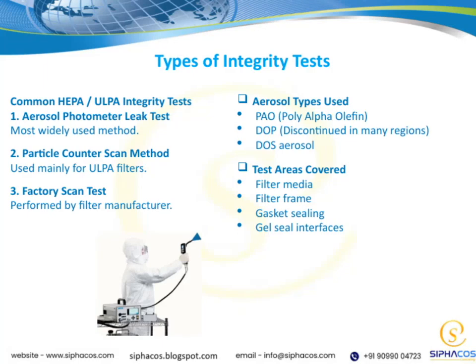Let's take a closer look at the types of aerosols we use in testing. We typically work with PAO, or polyalphaolefin, which is a standard aerosol for these tests. DOP, or dioctyl phthalate, was once common, but has been discontinued in many regions due to health and safety concerns. Lastly, we have DOS aerosol, which is another option, especially in specific applications.